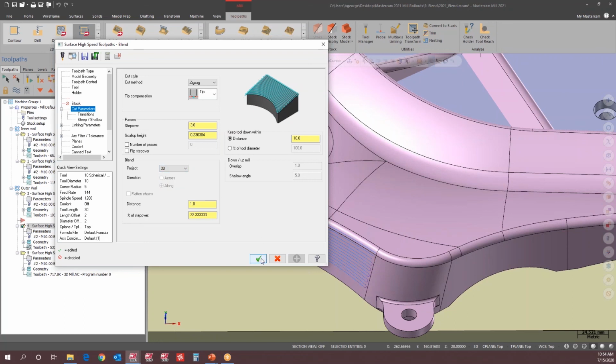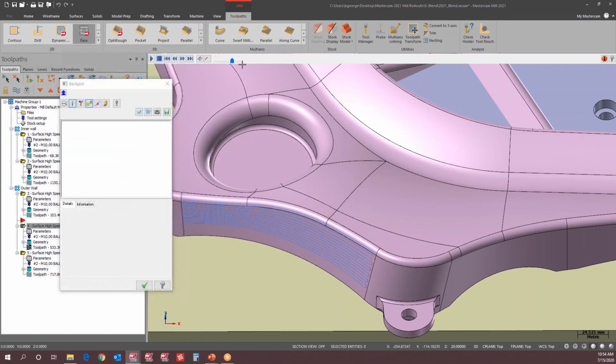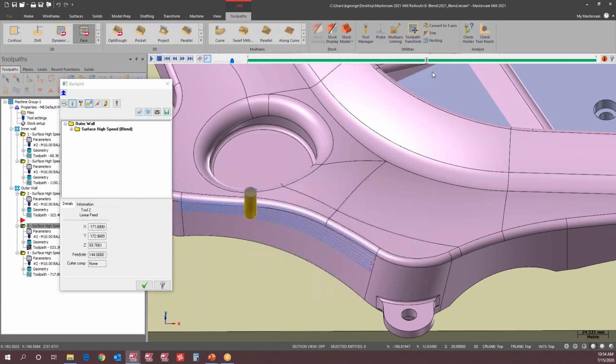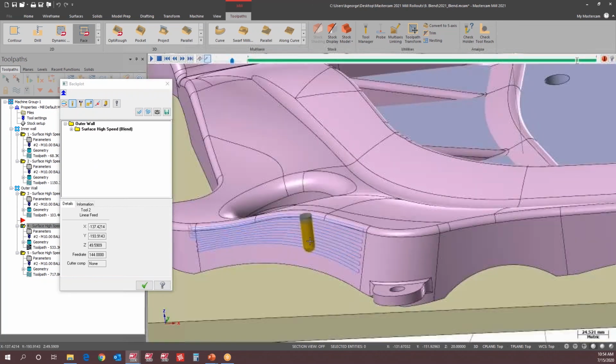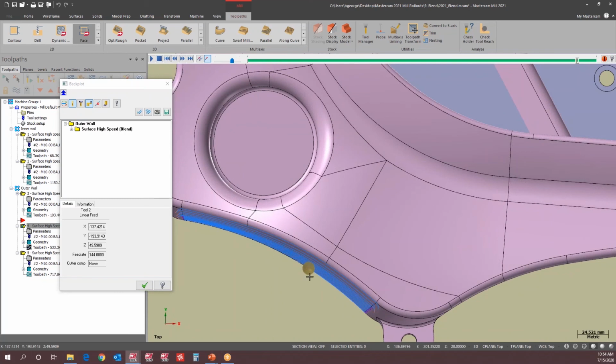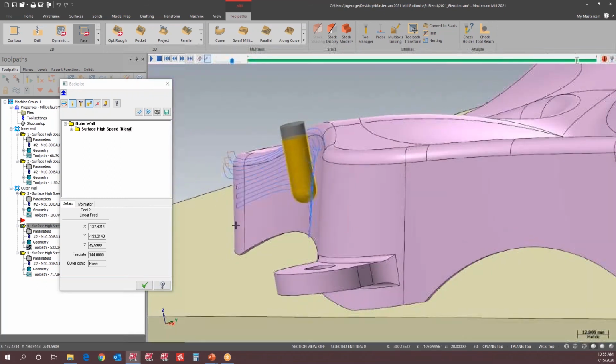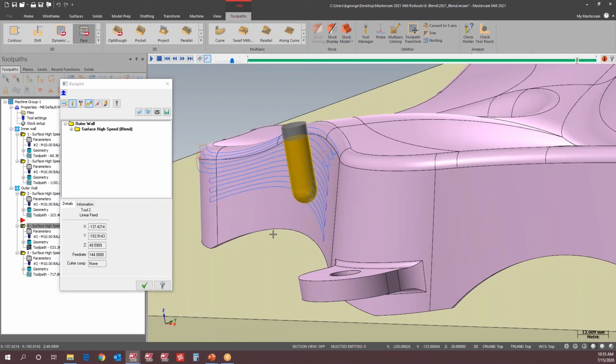So the first thing we can see with this 3D toolpath is now it's actually got slices that look like the same step over. They actually look correct now. The only problem is, because we're still blending in between these cuts, my center of tool is still on that bottom chain. Well, that's an issue too, because if we take a look at this, it's obviously not cutting that whole surface.